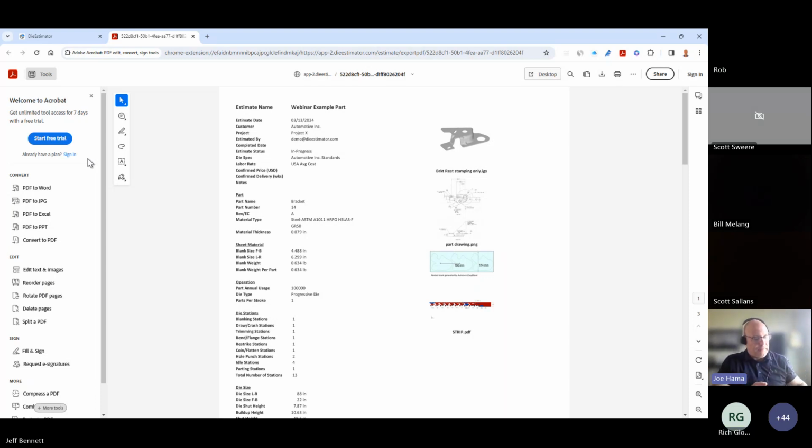So for an example, as Jeff alluded to, there's different ways to come up with getting a blank. There's free services on the internet. There are other companies that offer that type of blanking service. And of course, also nesting as well. So ultimately, you want to provide yourself not only the blank, but come up with your progression as well. That gives you all that's needed to use as a prompt, so that you can walk through the different steps of showing what type of features are actually going to be used on that part, so that it can develop the punching blocks, can develop the piercings.